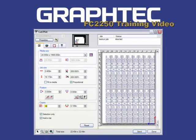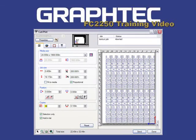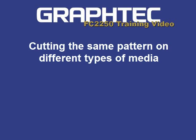Your software usually has a better way of handling copies like this because you can visually see the layout. So where can the copy button be a benefit to you? One of the key benefits is when you're cutting the same shape but on several different types of media, where each one needs a different cutting condition. To do this from the computer, you'd have to resend the job over and over again.